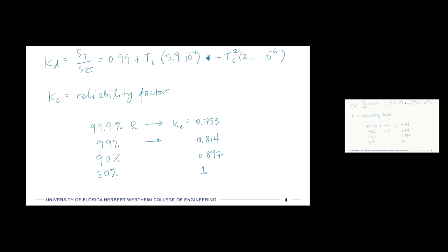And you can also do the same thing for, what's the highest value I can get? Well, the highest value is 1. Our endurance limit is unchanged. But the amount of money that would have to be spent to make the component have an endurance limit modification of 1 would be significant and probably not worth the payoff for whatever the operational component is. So I gave you these factors to try to estimate from all of the different empirical curves. We have S-N curves.